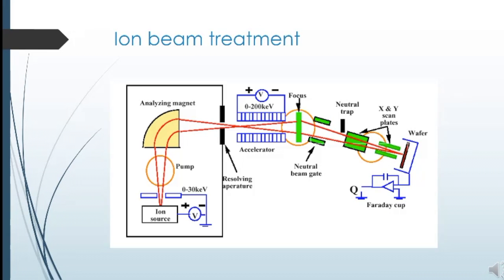Ion beam implantation. In this process, accelerated ions are injected into the surface of a material, and the surface properties of the material are modified, largely used for metallic biomaterials. The process involves the implantation of the desired ions at high kinetic energies on a localized surface zone. Applications of such a process include improvement in hardness, wear, corrosion, toughness, and bioreactivity. One example shows that silver ions implanted into polystyrene allow cell attachment onto the surface.